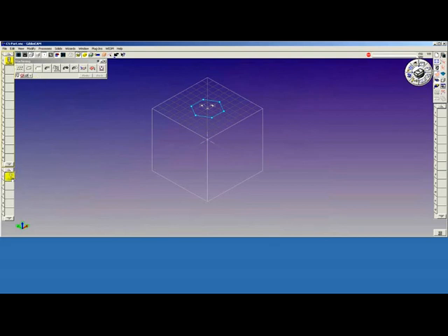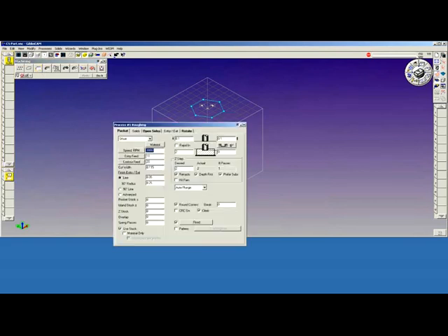Drag it down. Bring down the roughing tile. Place it on top of that. And I'm going to select an offset pocket. RPMs of 3,000, entry feed of 10, cut feed of 20, cut width 115 is a default to the radius of the cutter minus the corner radius. Half the cutter is 125 thousandths minus my 10 thousandths corner radius gives me 115 thousandths cut width.